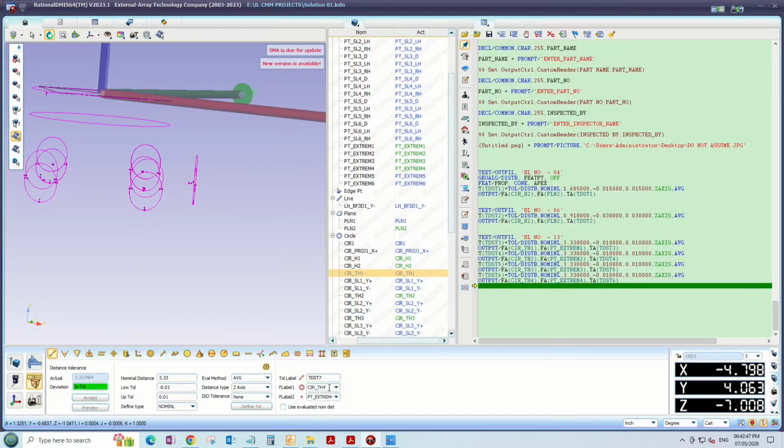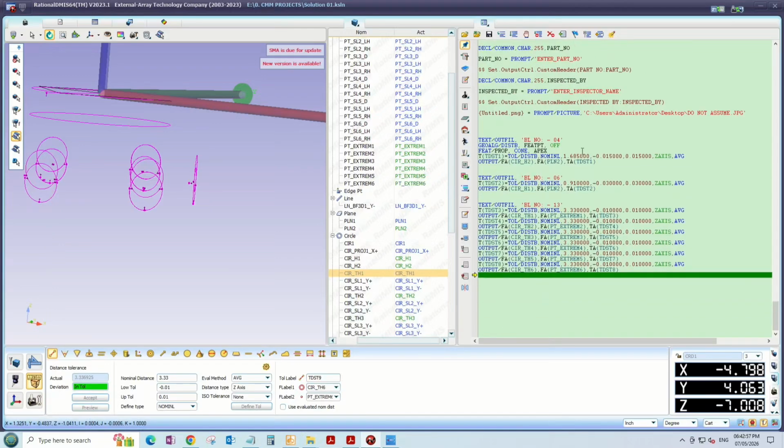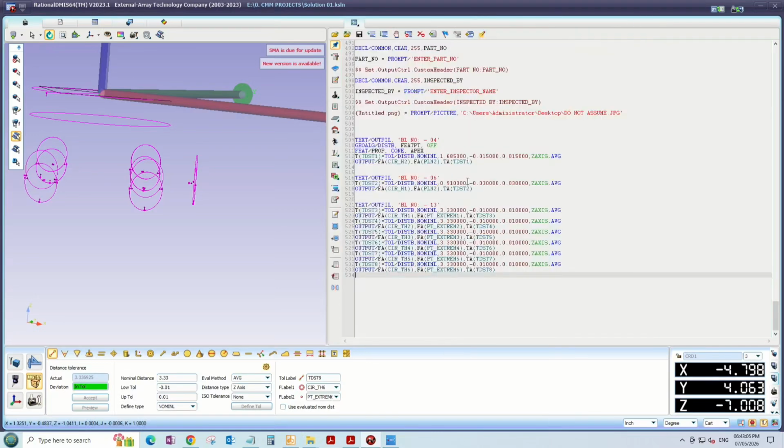Now I want an extreme point. So here it is. I'm going to take the extreme point from the front view. I can see a preview of the extreme point, Z minus. Okay, simply I'm going to cut and paste it above, because the construction feature should be separate.